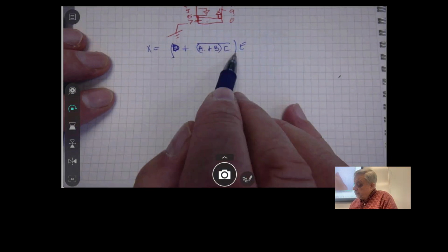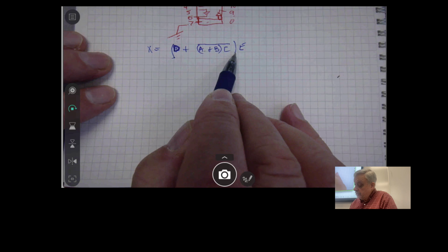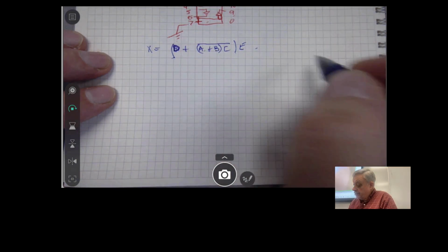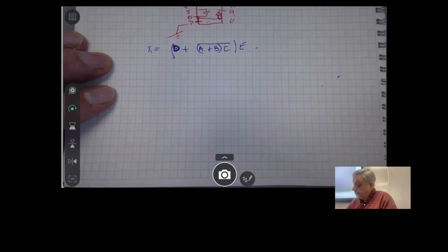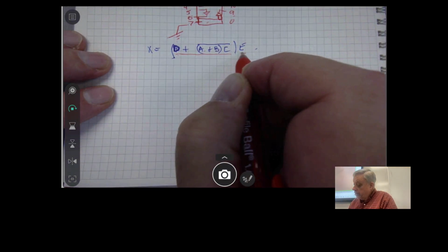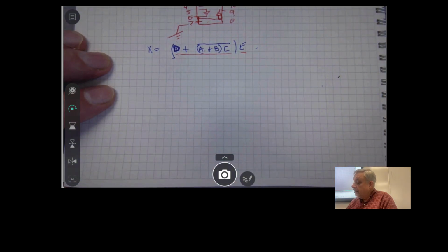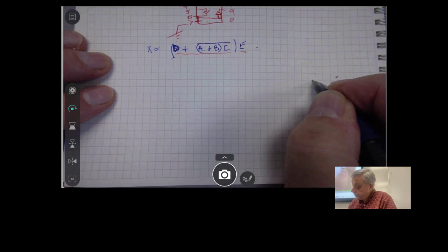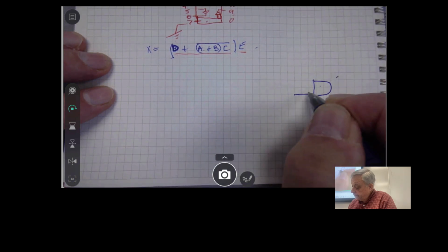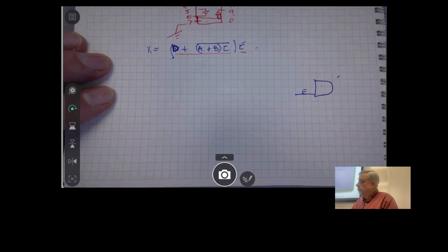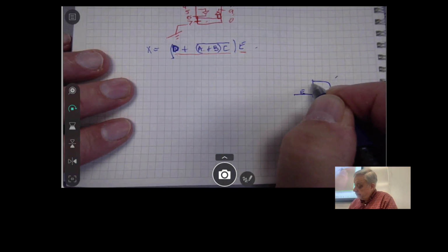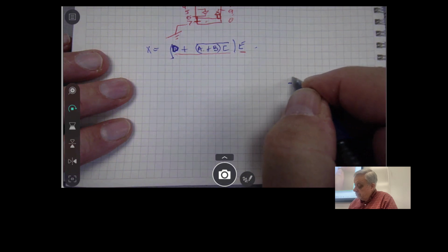So if I've got this expression, how do I work backwards? I'm going to go to the output. This is the final output. And I notice that I've got this term ANDed against E. So I've got A here, or E here. Take it backwards.